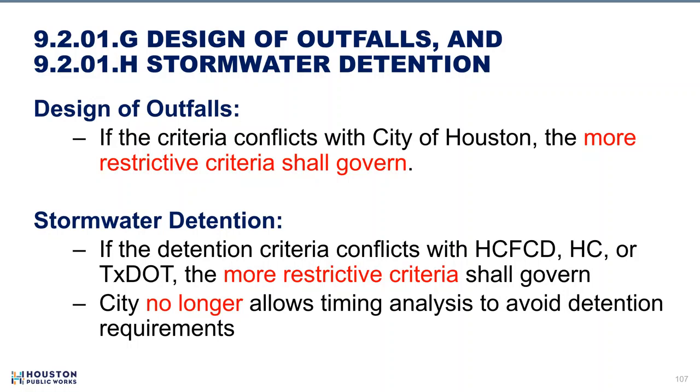What about stormwater detention? That creates even more different opinions from different engineering firms or property owners. So we state that if the detention criteria has a conflict with Harris County Flood Control District, Harris County, or TxDOT, the more restrictive criteria should govern.